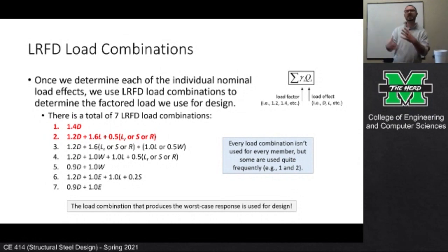One of the other things I want you to think about is that there are limit states that can affect a design that aren't just during its completed stage. Sometimes the worst case design situation is while the structure is being built. For instance, in bridge engineering, there are instances where the worst case limit state is actually the stresses it endures during construction, not when it's complete, because while it's being constructed, the elements themselves are weaker. It's like putting together an erector set: sometimes the structure is kind of flimsy until it's finally put together, and then it's strong.